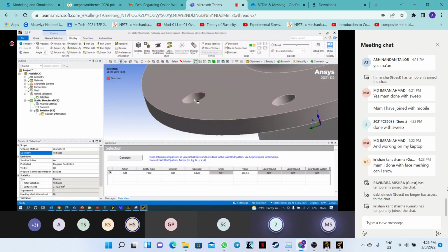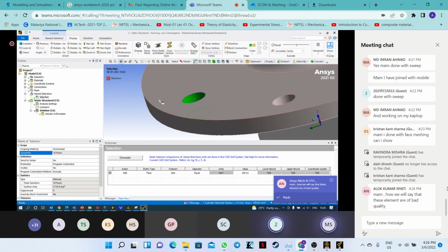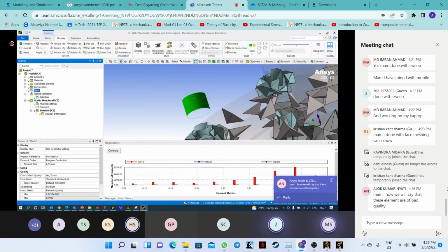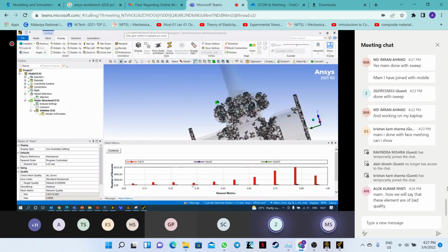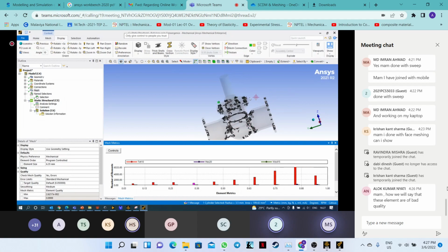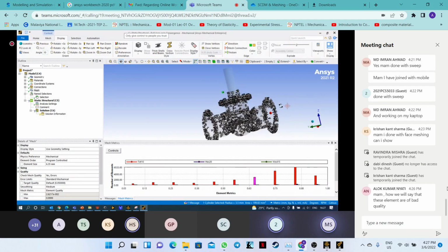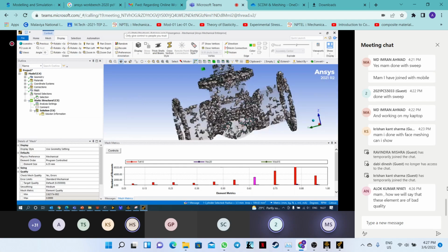Next, same thing, I'll select one of these holes. See, how do we say that the elements are of poor quality? These are 0.38 quality criteria elements, and when we have 0.72 average elements coming up, they are good elements. All these elements that are generated are of good quality. So now we have to struggle to bring all these elements from 0.03 to 0.65 into good quality from bad quality. So how exactly do you say these are good quality and these are bad quality?